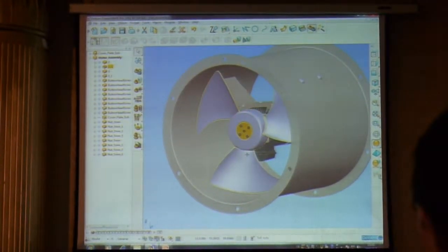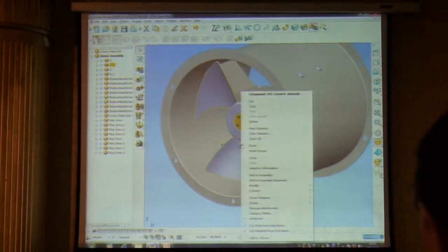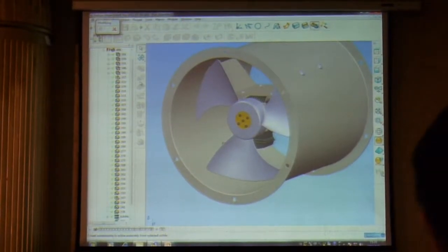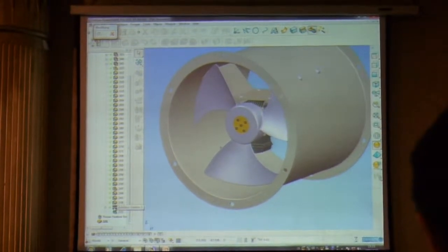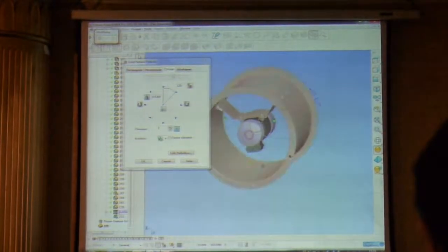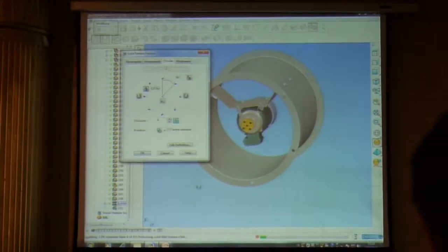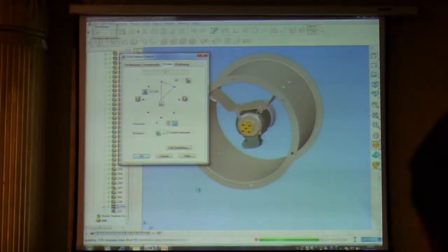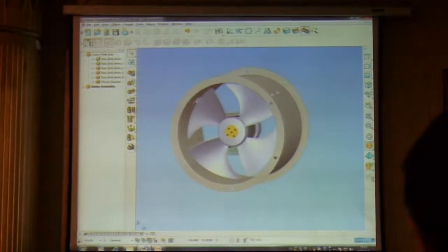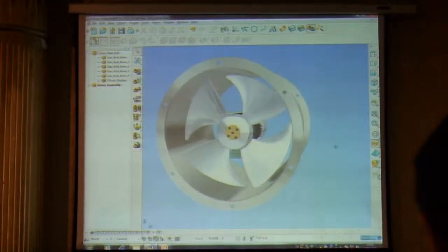Now also, we can make changes to this. So if I select the main blade geometry, I could say I actually wish to modify that geometry. This will expose the history tree of the solid. So I can work down the history tree, I can find the operation that I wish to change, so in this case the number of instances of the blade, and I could choose to change that from 3 to maybe 4 blades, and the whole history tree will very rapidly update, and you can see now we've completely changed that fan from 3 blades to 4 blades.